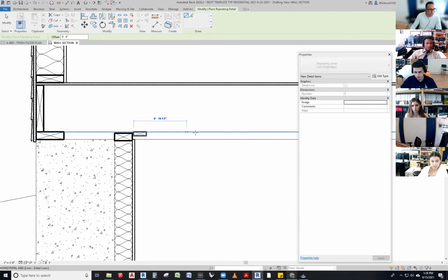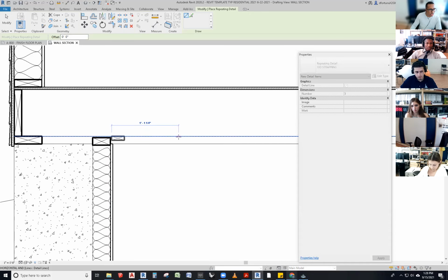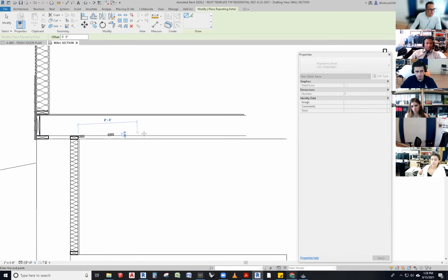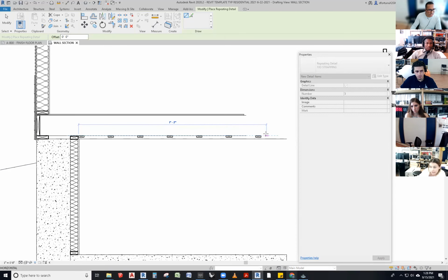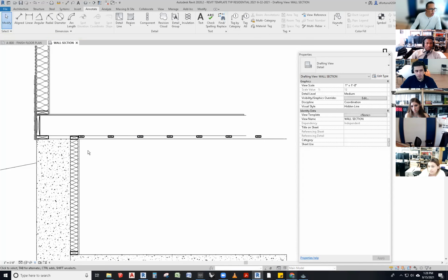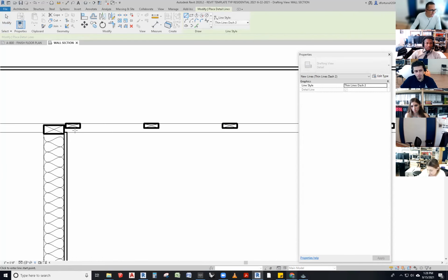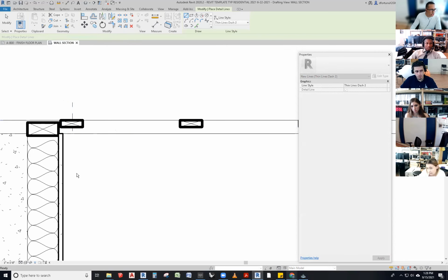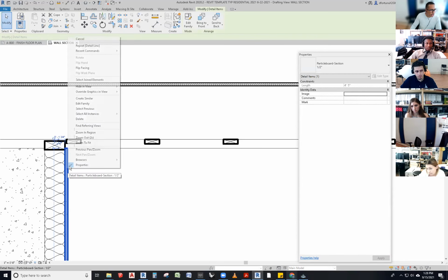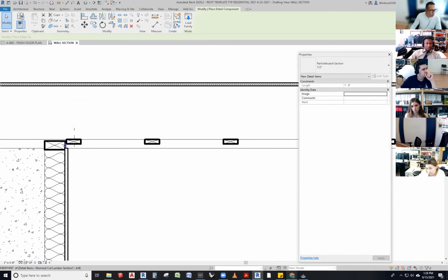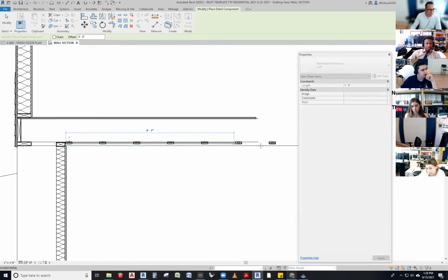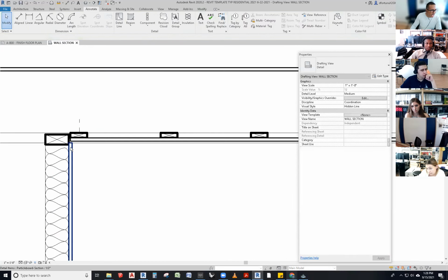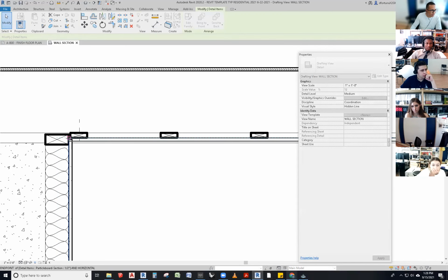They attach directly to the underside of the structure. And they go perpendicular to it. That's why you do see it in this case. What do we use that for? Well, that gets attached to your structure, and then your finished gypsum wall board gets attached to it. And in this case, now you have a nicely finished ceiling.